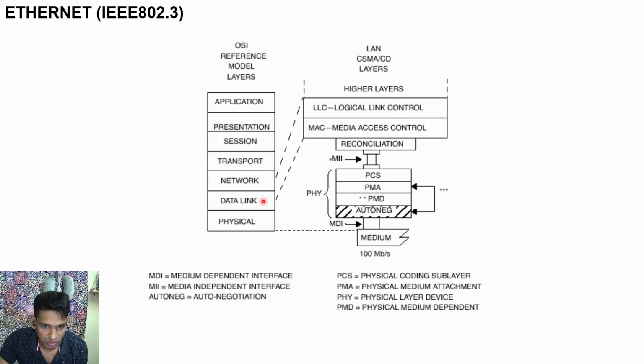So your network switch works in the data link layer, and your IP device works in the network layer, and the gateway also works in the IP layer. And suppose the gateway is a protocol gateway, it works in the transport layer. For example, a 61850 gateway, which converts from 61850 to 104. It is a protocol gateway, not a network gateway. So the protocol gateway works in the transport layer. A network gateway works in the network layer like a router. So these are the distinctions between devices.